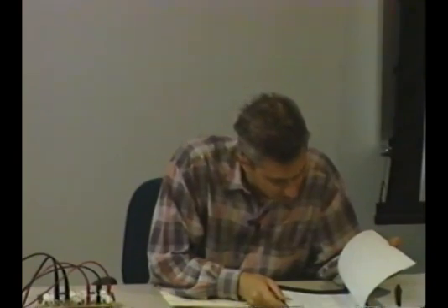Okay, any questions about this or how it works, or what you can do with one? You don't have to determine power. What's that? Power dissipation. Oh, for this guy? No, I don't know. Let's find out. It doesn't say. It'll be here somewhere, but I'm sure it's relatively small. Oh, here you go. It's 670 milliwatts. No, that's not it. You have to look it up. It depends on various things like the power supply voltage and all sorts of other stuff. But yeah, not a whole lot. It doesn't run that hot. It's slightly warm. That's all. So I'd say it's a quarter watt, something like that.